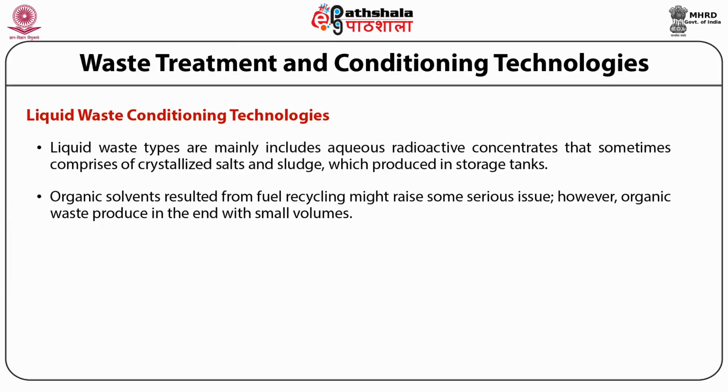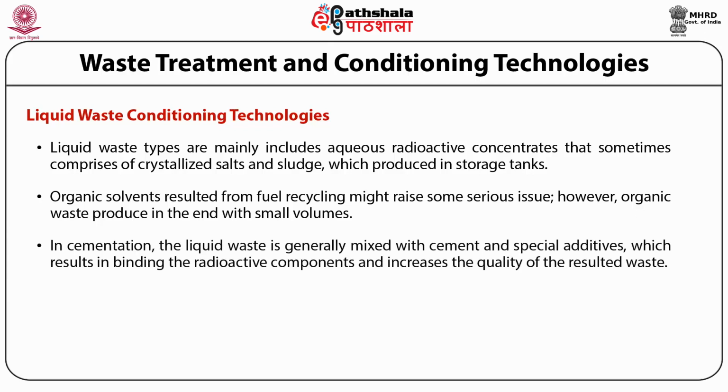Cementation and bituminization are well developed methods for liquid waste conditioning. Nowadays, high temperature technologies, including vitrification, plasma torch, etc., are being investigated and tested. In cementation, the liquid waste is generally mixed with cement and special additives, resulting in the binding of radioactive components and increasing the quality of the resulting waste.